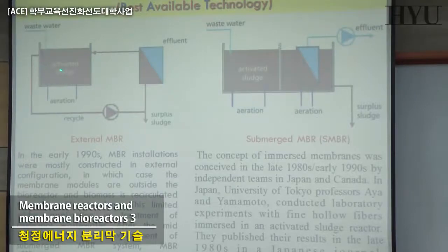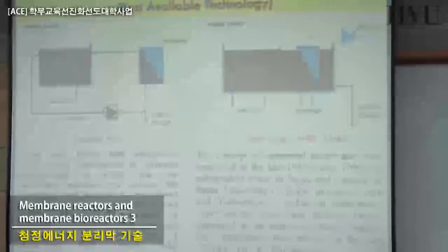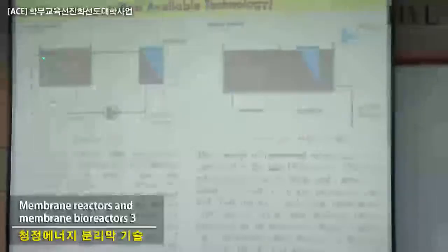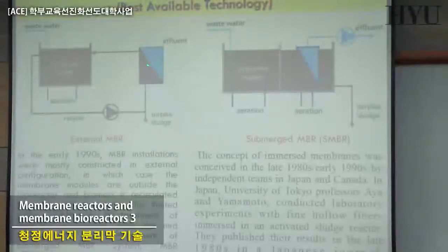But that is the activated sludge. That means the typical biological system that people are using today and were using until yesterday everywhere, where you have some microorganisms that are supposed to transform all this dirty stuff present in the municipal wastewater through decomposition into ammonia, nitrogen, etc. And you can improve significantly the efficiency of this system just by combining it with a traditional membrane system.